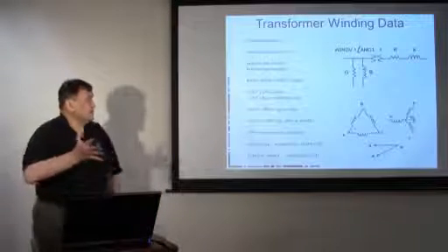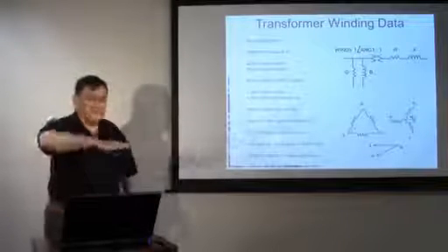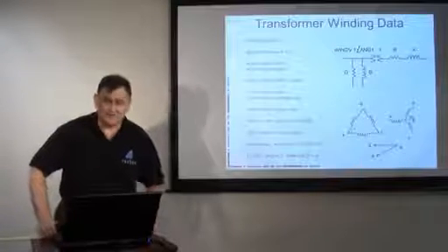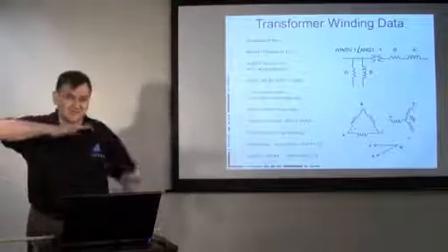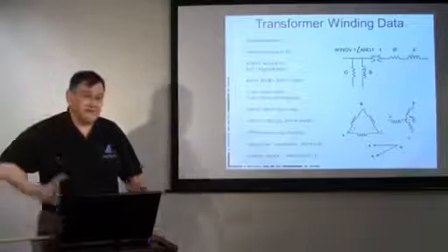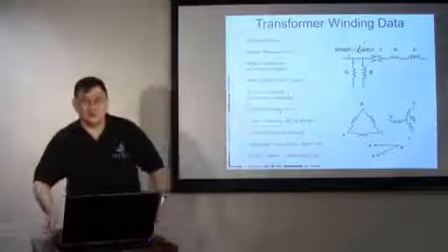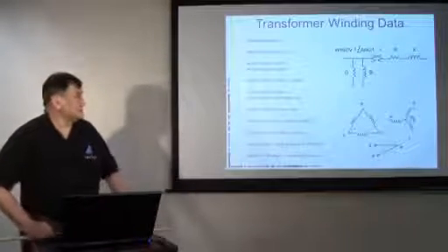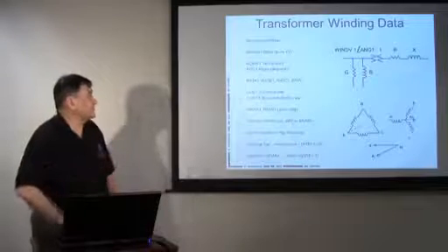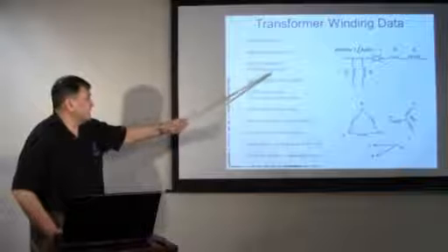It also has data associated with the winding. It can have a tap. The tap ratio is, we went through the whole process of transformers in the voltage class, remember? That tap can raise or lower the voltage by varying from a nominal value. And it can have a phase shift, and that's what the angle is. Again, remember we talked about phase shifters, and we talked about star to delta transformations, so that's what those values can be used for. It has a nominal voltage, it can have an angle.